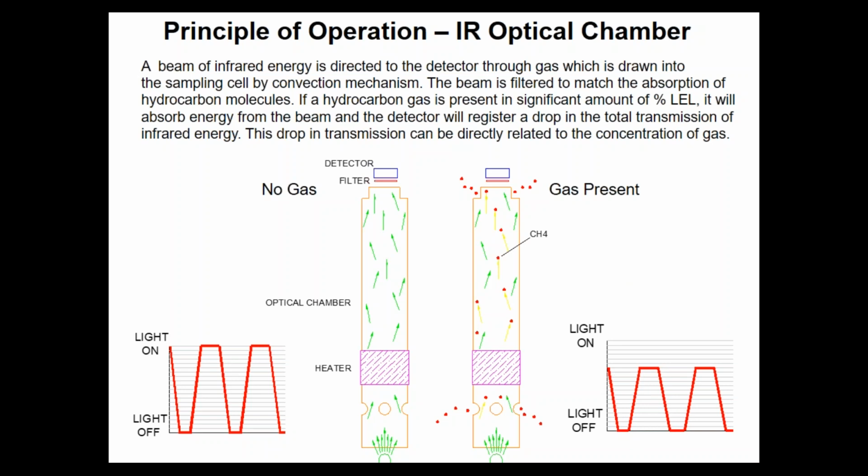And that's the simplicity of an IR detector. The complications are enormous, okay? When we design this thing, we probably have 30 or 40 algorithms that have to be put in to compensate for moisture, temperature, atmospheric conditions, change in light source, and change in detector failure over time. So all these things are determined up front.